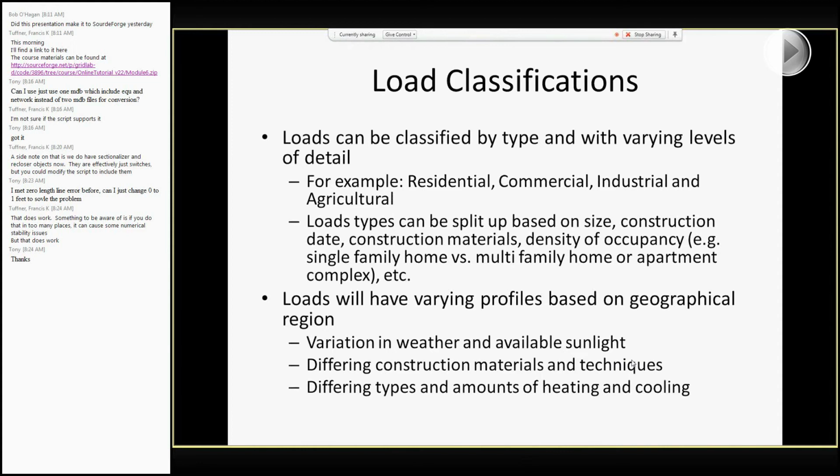So the way that we do this, the first portion is typically a little bit of a manual process. We really want to classify these loads. One way we've done this in the past is, for example, with the taxonomy feeders, we extracted that information from the databases because it was already available. They had things like residential versus commercial, industrial, agricultural. And where we didn't, we contacted the utilities, worked with them, and were able to pull that information.